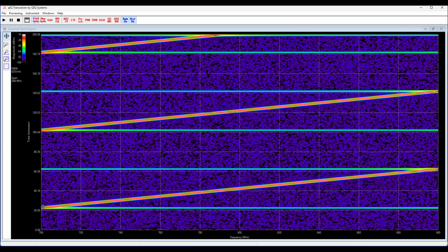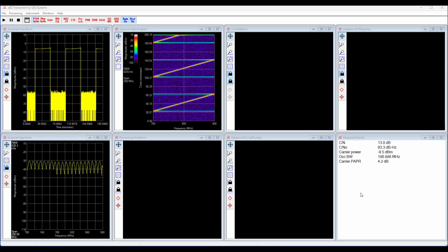We're 100 megahertz below, and we start our frequency chirp, and the frequency moves up in a positive direction during the time that the chirp plays out, and then it ends up at 100 megahertz above the carrier, and this total time here is the 40 microseconds, and then it's off for 40 microseconds, and then it's on for 40, and so forth. So let's now go turn on our arbitrary waveform equalization.